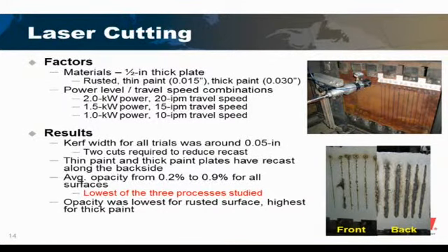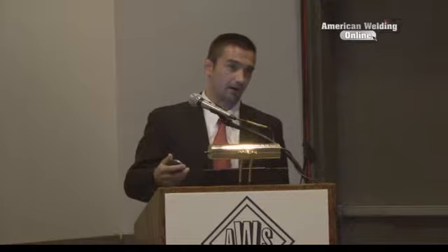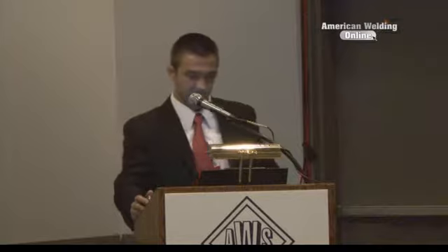So in the next task, what we focused on was laser cutting. We didn't optimize the laser cutting process, but we wanted to get baseline conditions, just so that we have something to compare to what we got for oxyfuel cutting and plasma. So the materials, again, we looked at 1/2 inch thick, rusted, thin paint, and thick paint. We did some preliminary trials to develop our cutting conditions, and we found that a power to travel speed ratio of 0.1 generally resulted in